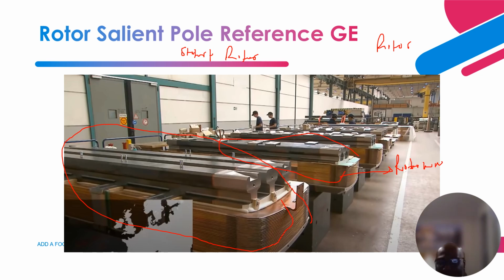So think about it. A typical generator has about 100 of these poles, right? So what is the revolution per minute? It is 120 times 60 over the number of poles, 100, right? So that is about 72 RPM. That's how slow a speed the generator will turn.